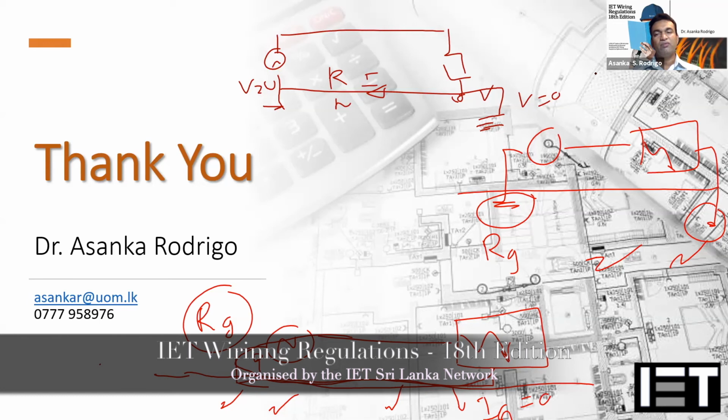For example, when you are installing precast for windows and doors, there can be certain cable connections to the equipotential bonding, or in some locations you can run an equipotential earth bar around the building, where you can connect all these things to that equipotential bonding bar.